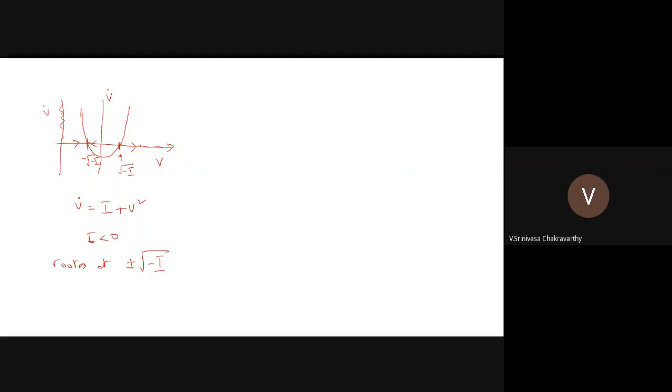And therefore, what we do is, if it reaches some value, which we'll call V peak, we just reset it. Imagine that resetting happens something like this. Let's say we reset to this point, and I'll call that V reset. Then what happens? It will creep back. Once it reaches here, I'm quickly putting it back here, and it will creep back to this point. And once it reaches, it stays there. So this point is like the resting state. I'll call this V rest.